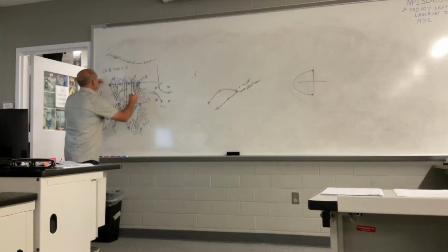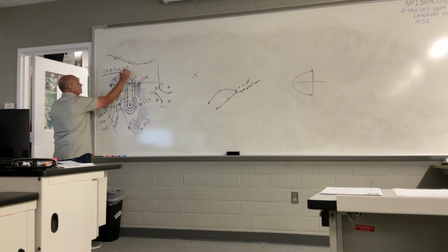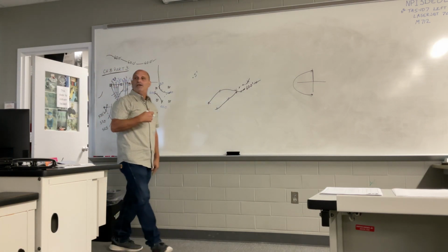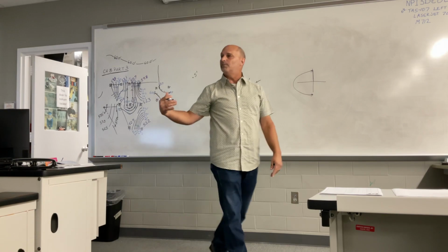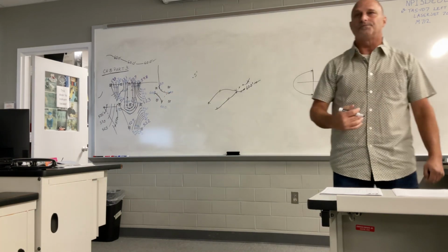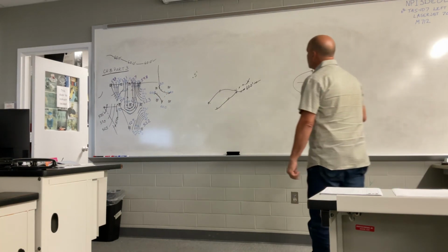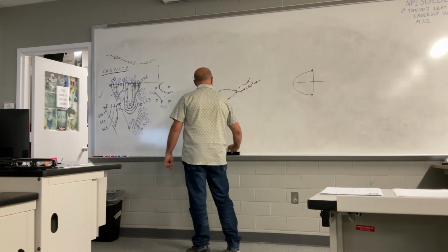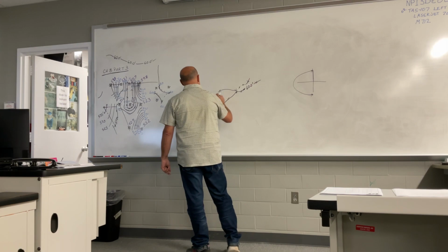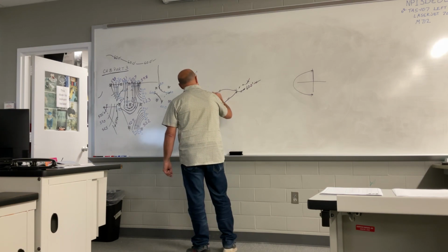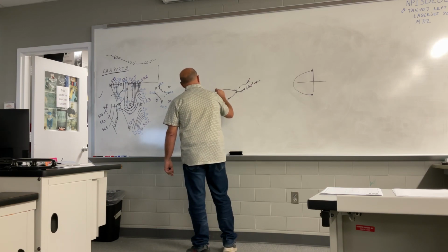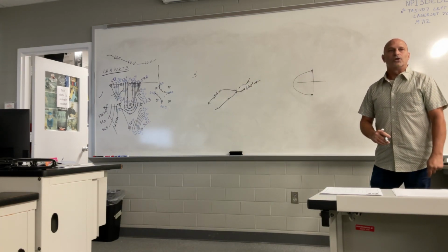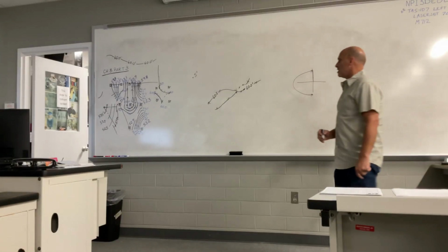Your next chapter review to do for the next week is chapter 8, part 3. Chapter 8 talks about contours, so that'll give you a little bit of info possibly on this. Whenever you label your contours, we're going to have two different labels or two different contour line weights. Our even feet contours are going to be what's called an index contour.